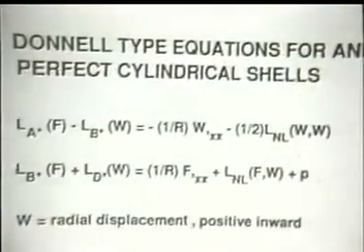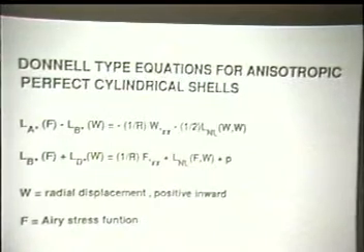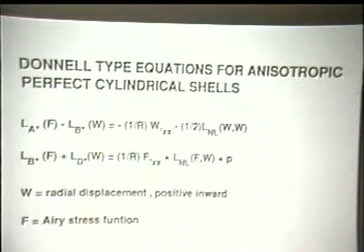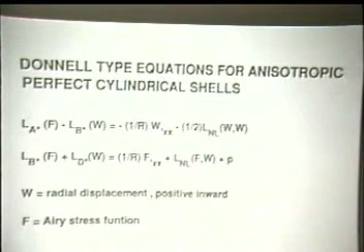Also, in aerospace engineering, one is at this moment very heavily interested in the so-called anisotropic shells. Those are composite shells made of all kinds of fiber reinforced materials, building up the wall in different layers, and you can essentially tailor your strengths very conveniently.